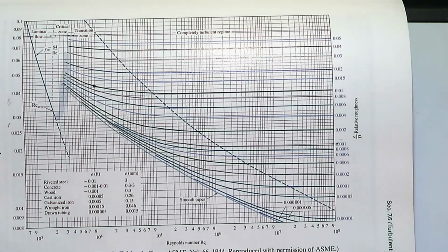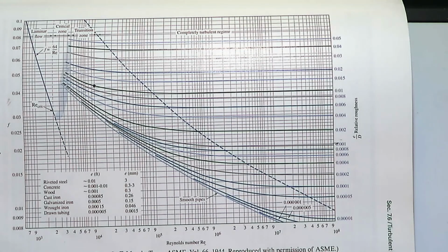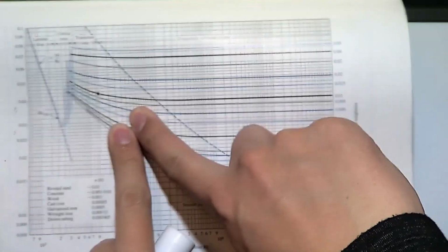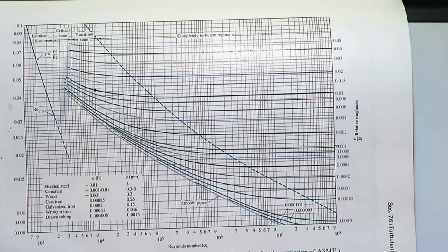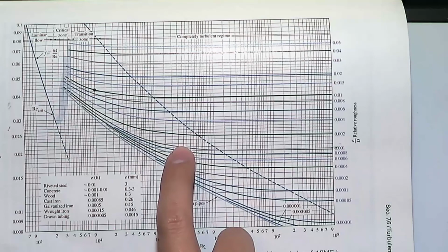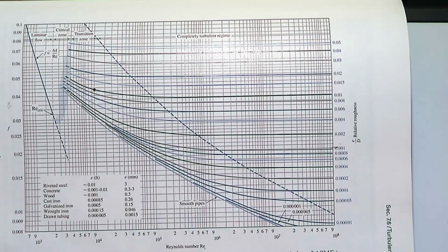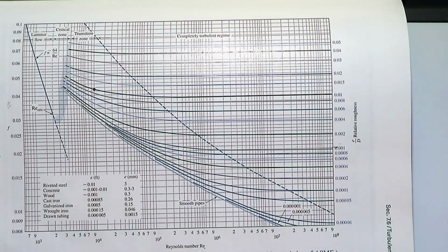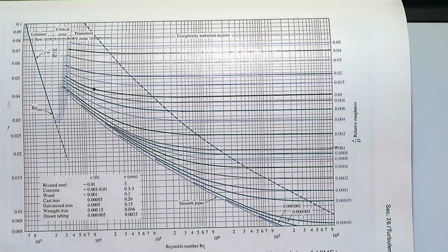You follow that gray line, the curved gray line that starts around your mark over there? Mm-hmm. Okay. I was making sure. And you follow that curve, right? Staying your original distance off, right? Yeah, or a proportional one, because notice that as you curve more, your distance becomes closer. So it's actually staying a proportional distance away. So if you're at 2/10 of the way between the gray line and the black line, you've got to stay at 2/10 of the way between the gray line and the black line, which may be a shorter distance. Yes? There's a way to use an interpolation calculator in Excel. We're going to get to that. There are actually several equations that interpolate this for you.